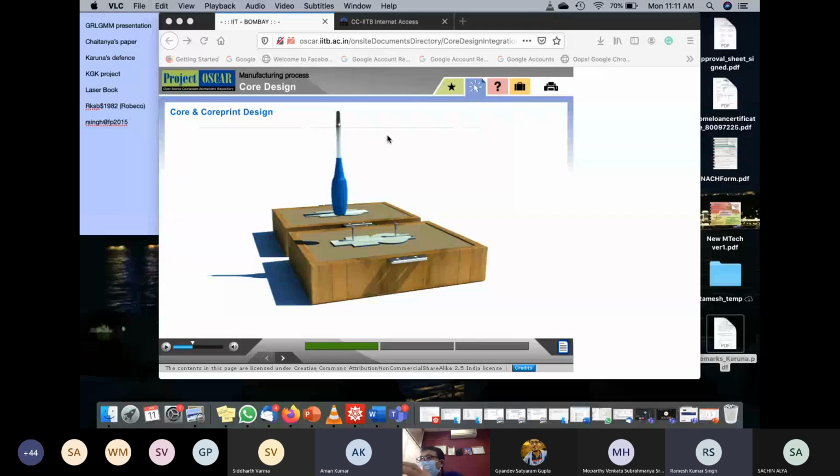So you have to apply pressure so that pressure driven flow goes in, like a flow through an annular pipe, right? But you have to give a pressure gradient because pressure is what drives the fluid, right? So I'll have to give a plunger. This plunger pushes the fluid into the cavity. When I'm doing sand casting, with the gravity head alone, I have the velocity due to the gravity head.